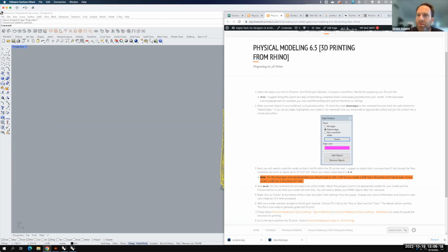So let's take my mesh, and we're going to scale it. And I'm going to have to turn on my vertex snap here so I can get the height. If we were struggling, we could also do it in the front view like this. And we could actually just go up a straight 600 feet. Oops.